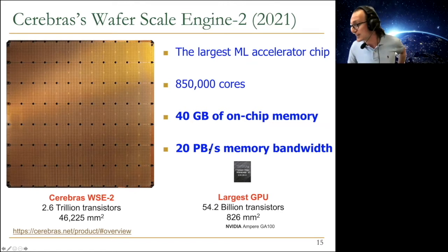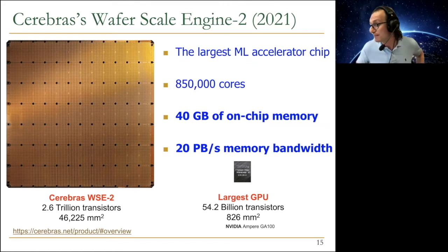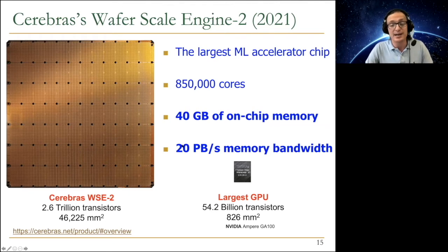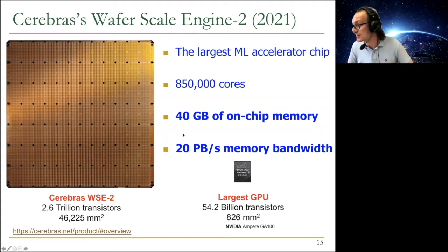So one question: what is a normal memory bandwidth for off-chip memory today? It's really on the order of, let's say, 100 gigabytes per second. A petabyte is clearly orders of magnitude larger than gigabytes per second, right? If you design extremely carefully, maybe you can imagine reaching terabytes per second, but petabytes per second is at some different scale, as you can see.